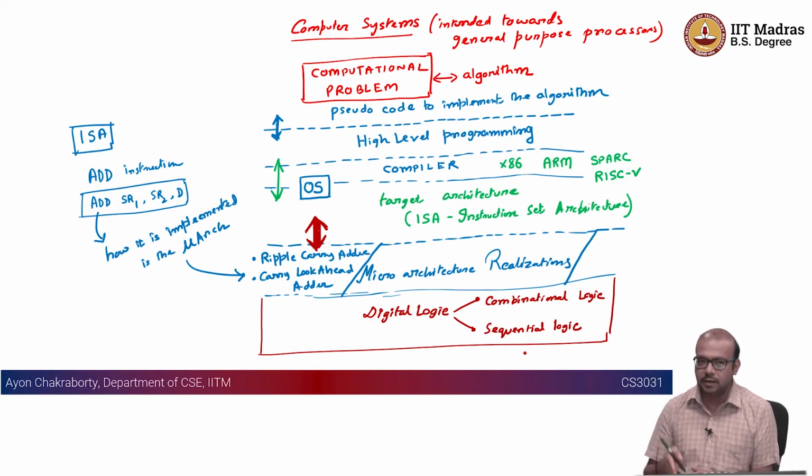So within a given clock, whatever is combinational in the circuit is going to be ready, right? And you need to make sure that you are not providing the clock even faster than the speed your combinational circuit is operating, right?